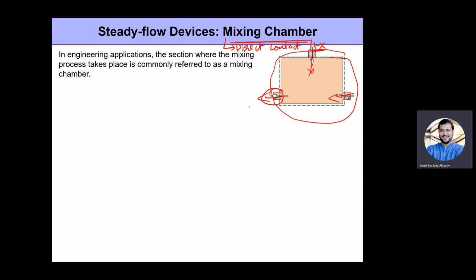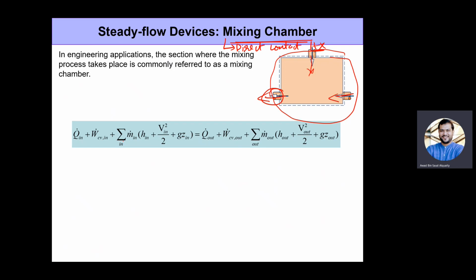All right. So when we talk about mixing chambers as well, we can start with the general energy balance. And we know that in a mixing chamber, its role is not to produce any heat. It does not take any heat input, it is zero. Of course, there's no work happening. All right. Work in and out both are zero. In general, the heat output is also zero. There's no heat loss to the surroundings because this device is really small. So there's not much space for heat transfer to occur in most cases to the surroundings. The changes in kinetic and potential energy are negligible, right?